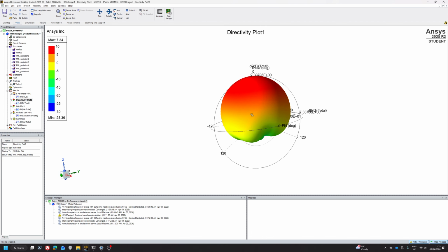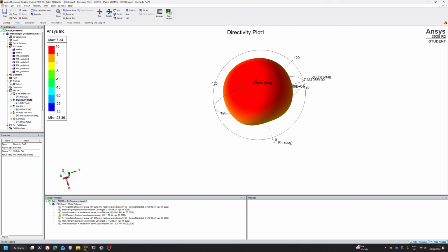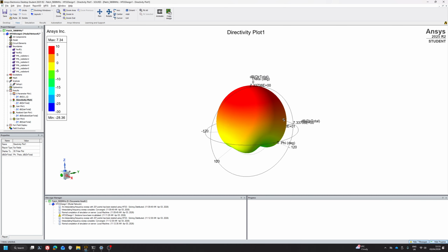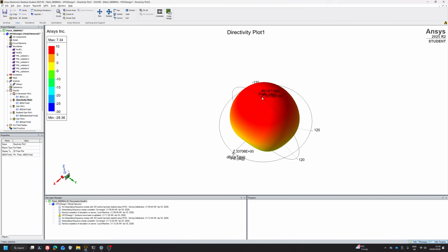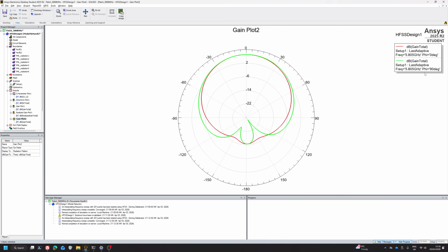What are those two cuts? If I have a look here, you see phi equal to 0 degree, and theta here equal to 0 degree. So theta is my elevation cut, so if I cut on theta like this, and I take this plane here from theta at 0 and going around to here again, I will have my phi 0 cut. If I'm looking from this cut over here, so theta going around here at 90 degrees, I have my theta with my phi cut, which is what I can see on both plots. So this is it for this video.